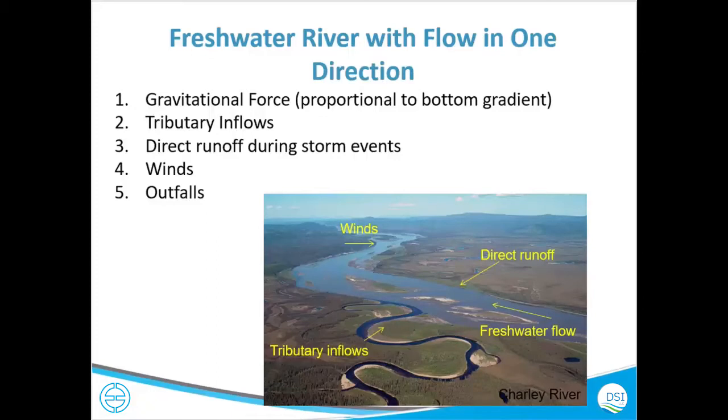Bathymetry and shoreline is always important. Here you see it's a meandering, right? Now if you try to create a Cartesian grid, that means rectangular, you would end up having so many grids to fit this. But if you have a curvilinear grid that follows the channel, then you will end up having fewer cells that will let you do more modeling, more repetition until you get your goal.